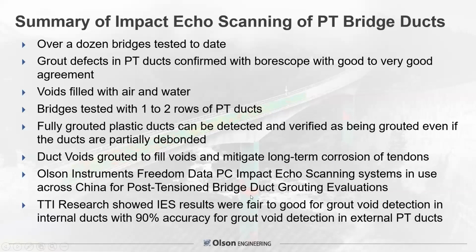We've sold a number of our systems in use across China. They've built so many post-tension bridge ducts in their many, many projects as they develop their infrastructure. They do this as routine quality assurance for new construction. And the TTI research showed the impact echo results were fair to good for grout void detection in the internal ducts, and very good with 90% accuracy for the grout void detection in the directly able to be tested external post-tension ducts.